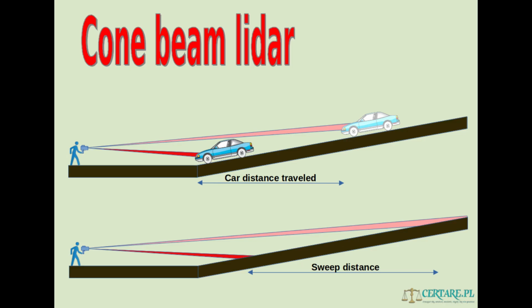And if the operator doesn't know what he's doing, he will try to get rid of that lidar growling, or fix that problem of the lidar complaining, by targeting slightly below the vehicle or above the vehicle. And what that will do is produce speed readings that have absolutely nothing to do with the speed of the vehicle.